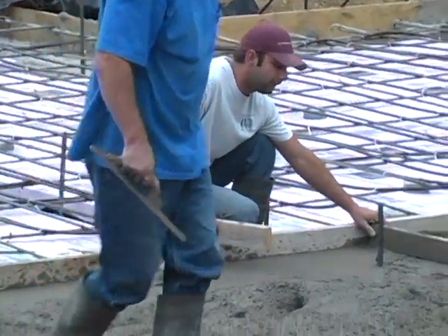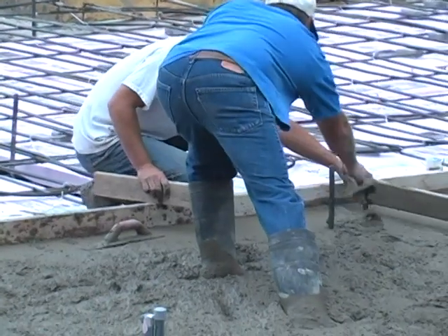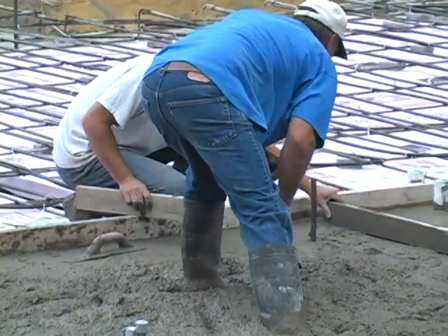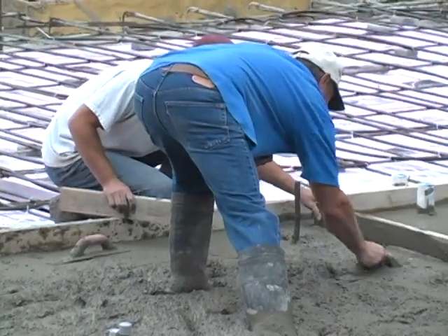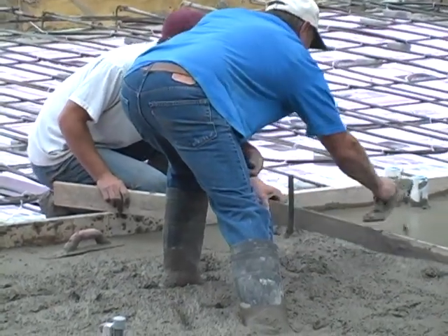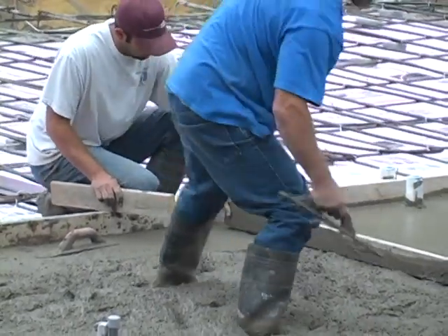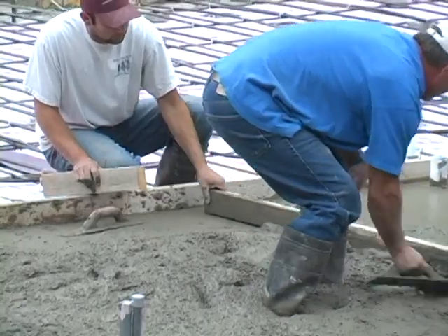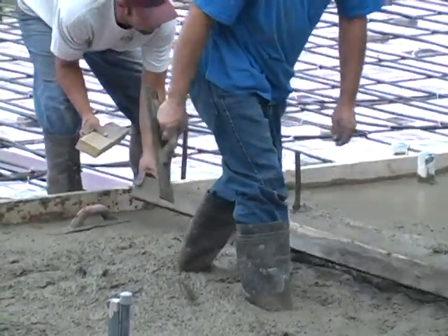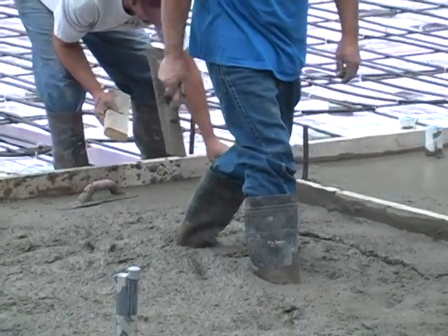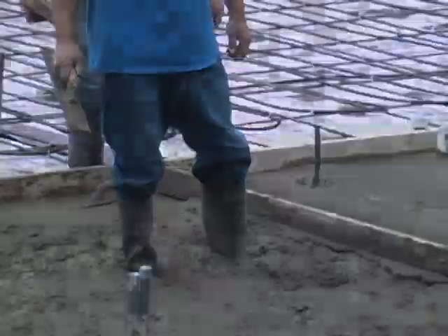Now, as you get better with the screed, you'll find that you won't have to actually hang the screed board on top of your guides. You'll be able to use just a straight 2x4 or another type of screed to just pull right across the surface. Now, this takes a lot of skill and a lot of practice, so it's not something I recommend on your first slab. But once you get this, it actually makes it a lot easier to use a mag float around the edges to create a level surface coming off of your form, and then just use a straight 2x4 to screed from there. When you get the skill, it makes it a lot easier.